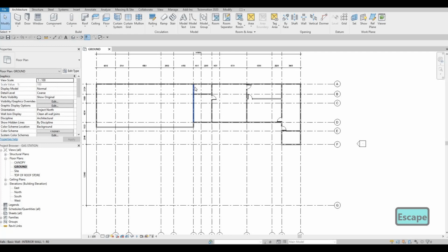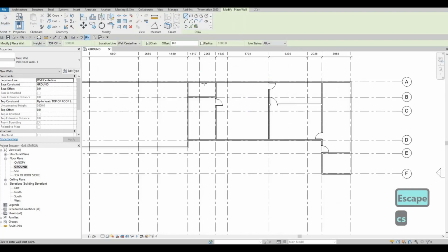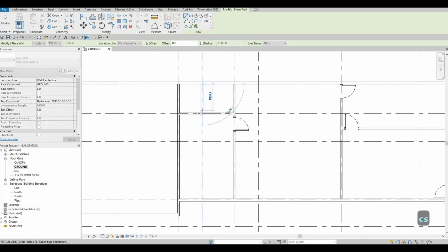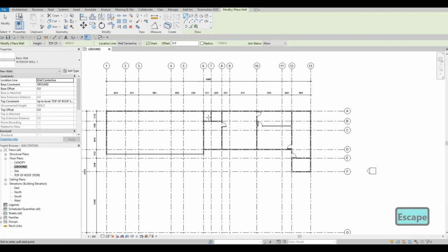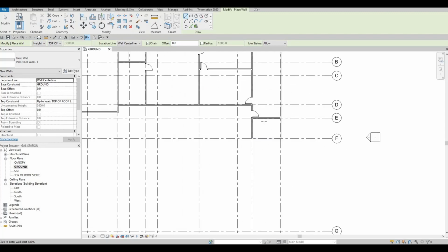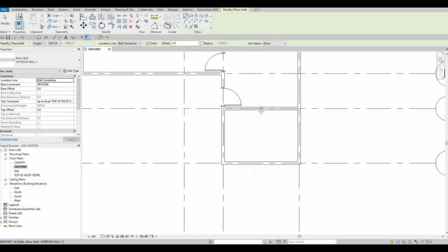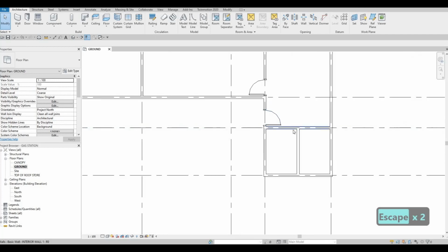So now, like I said, we need interior walls again. Select the interior wall that you know, or you could just select here or whatever. Once you see the interior wall, CS on that, and then let's add a wall right here to divide them all together. So that's B7 to A7. And then again, here, what we're gonna do is zoom in, and then we have the midpoint right here. We're going to use the midpoint so that everything goes all together.